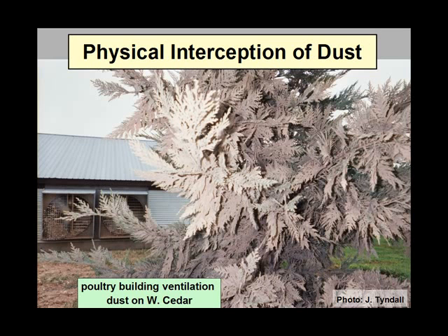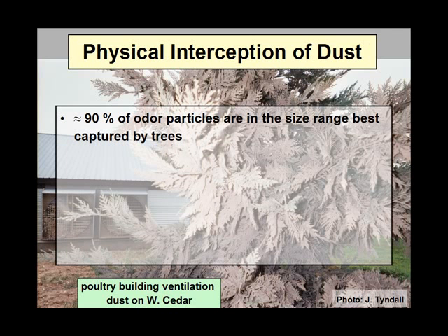Physical interception of dust. Now this is a picture from a poultry context. Poultry dust shows a lot better on the trees than swine dust does, so I opted to use this photo. But in general, we've done a lot of research showing the ability of trees to grab on and hold on to particulates. We've done a lot of research on the long-term health of trees in these kinds of situations and so on. I'll just give you a quick overview of some of the key details. 90% of the odor particles that are generated inside these buildings are in the size range that are best captured by trees.